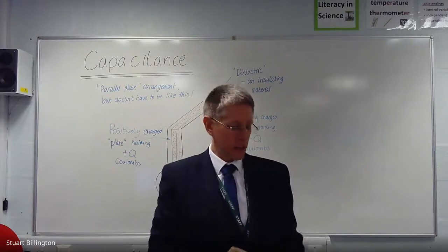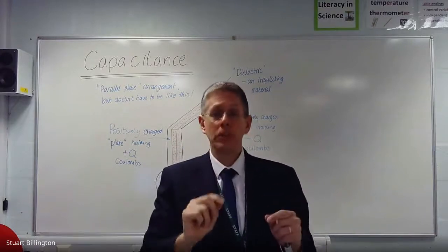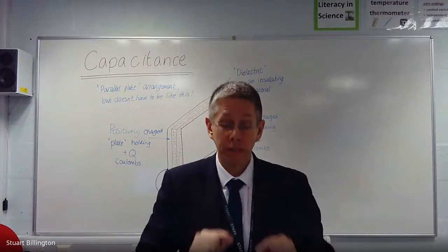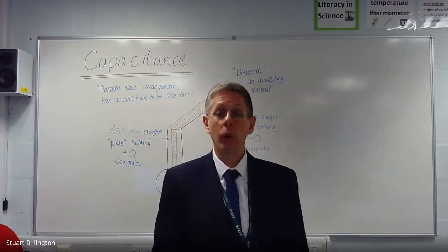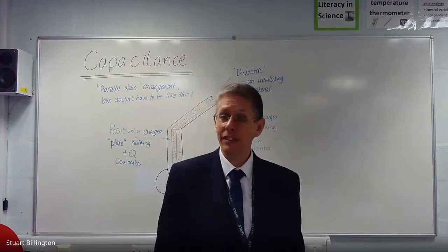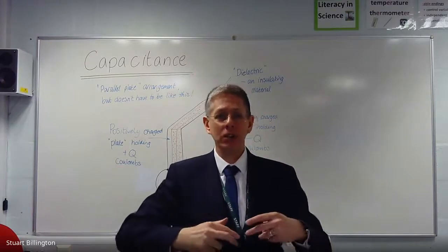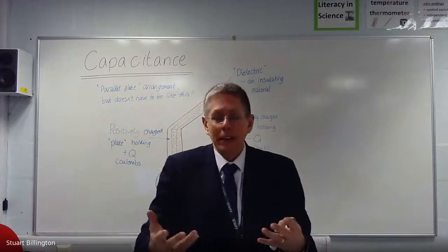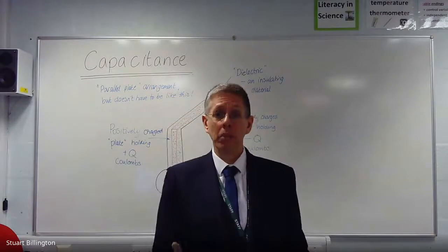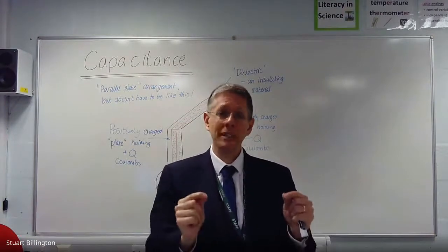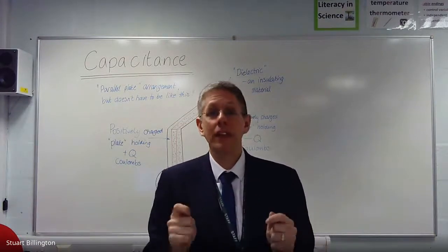What we're really talking about is the amount of charge at 1 volt. That's going to be however much charge is in it at 1 volt. We're going to call that the capacitance. And then the actual capacity, the maximum charge that it can store, might be a lot higher than that if we apply more than 1 volt to it. So capacitance rather than capacity.